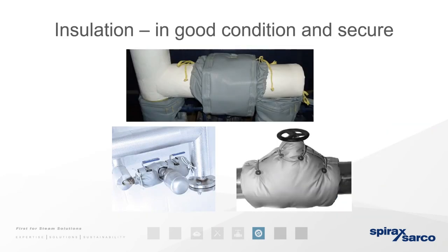Again, insulation in good condition, and it must be secured, absolutely. We just saw a little bit earlier that 10 bar gauge has 185 degrees Celsius. Having pipes that are uninsulated or valves that are exposed to these temperatures becomes a safety aspect, where people walk past it or have to handle it, and without the correct PPE can easily burn.